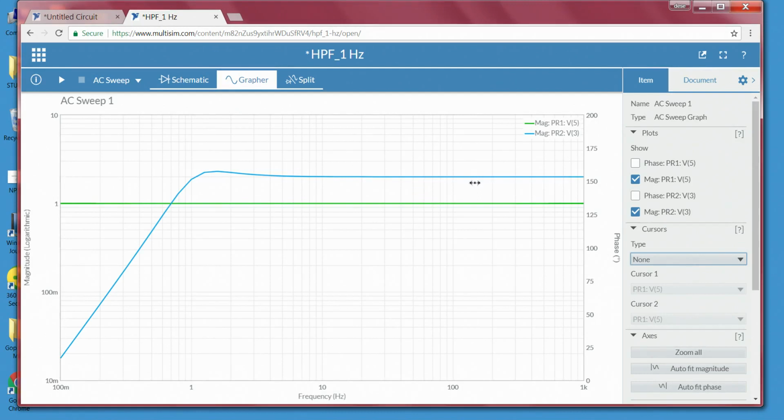If you remember correctly, the gain of the op amp is 2. So, that is the reason the output magnitude is double that of the input magnitude. Now, what about at different frequencies? No matter what frequency you are at, the input always has a magnitude of 1, whereas the output depends upon the frequency. It is slowly increasing and at one particular point it has become 2.